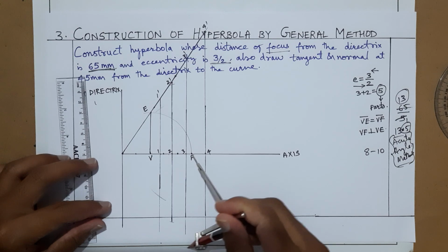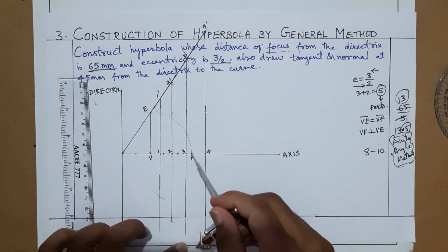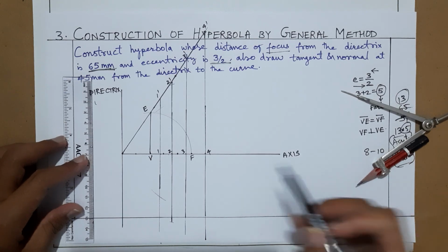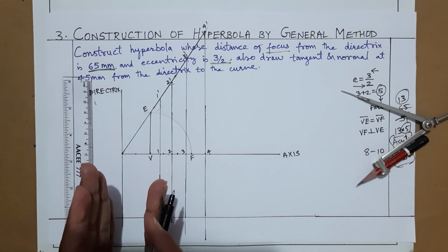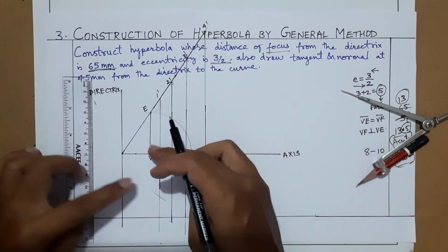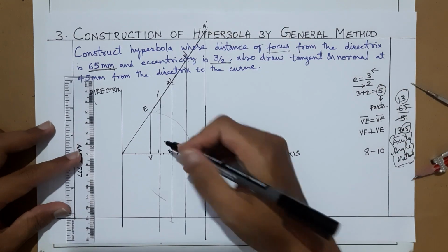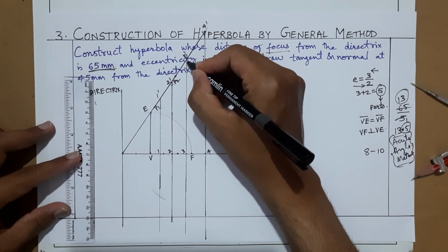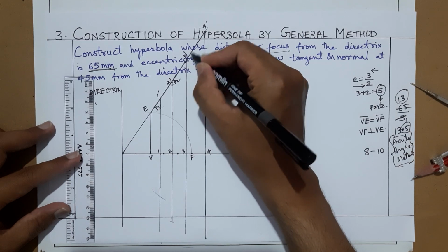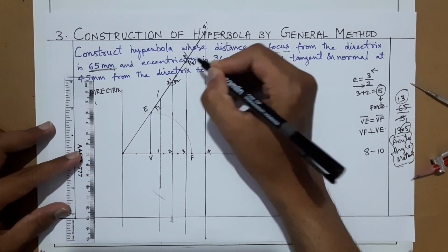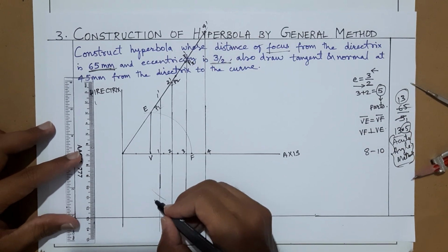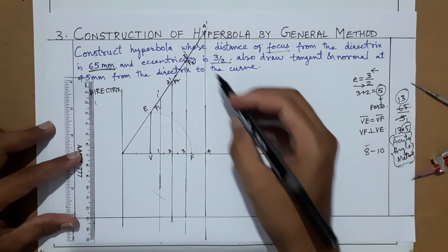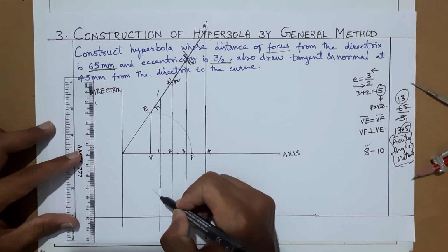So it is going beyond the limit of the drawing sheet, so I'll stop here. If you have a big drawing sheet, you have to continue the points. This hyperbolic curve will be wide open, so it will go like this. Now say this as point 1, this as point 2, here just below the generator is your arc P3, and after marking the last, say the last number is P8. After that you have to continue here as P9.